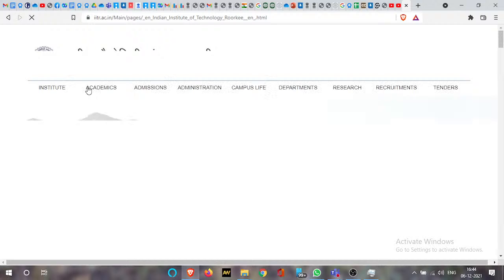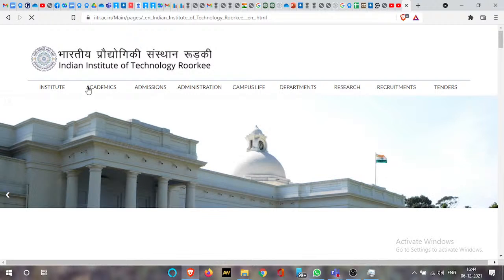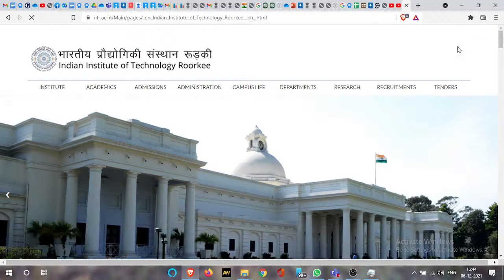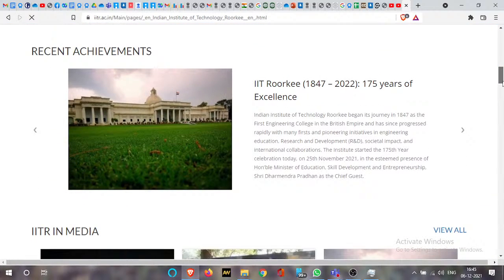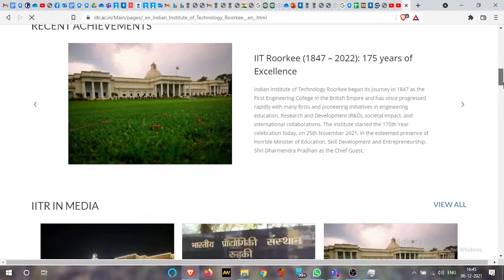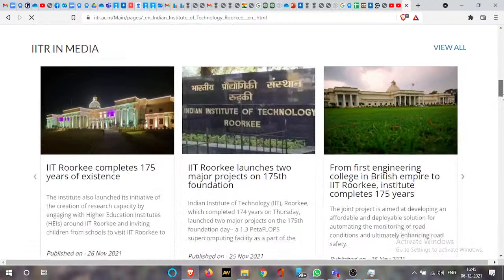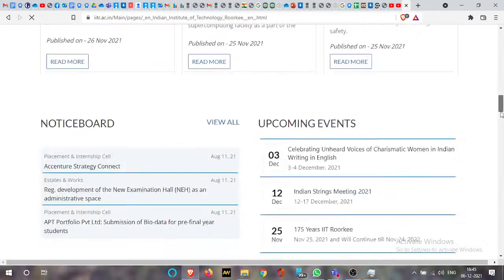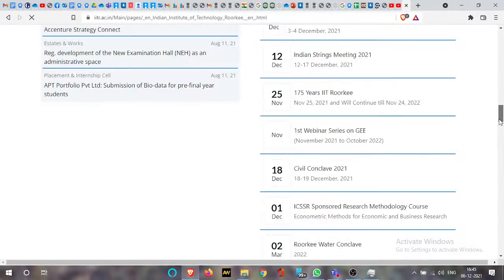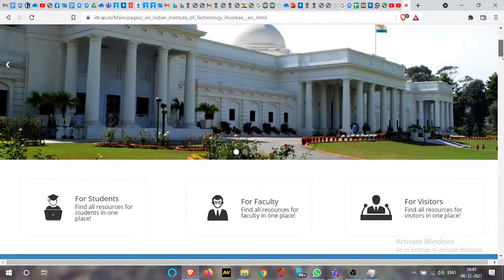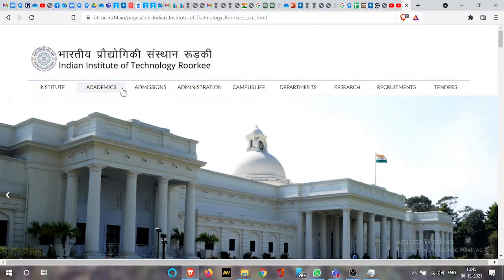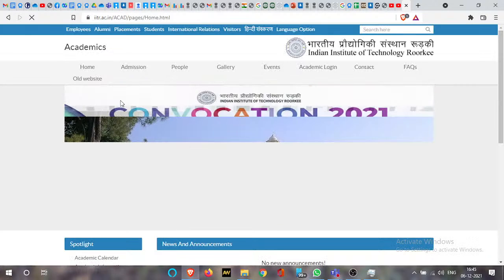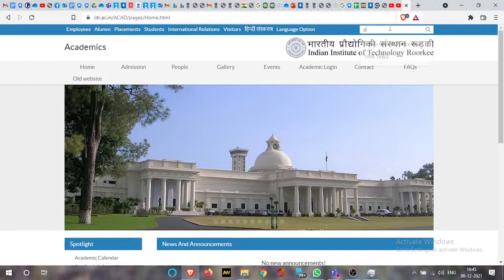So this is basically a cartoon to just show you how spin up electrons can easily transmit through this channel. If the alignment of one ferromagnetic layer and another ferromagnetic layer is parallel to each other, the electron which is anti-parallel to this can easily scatter, but the electron which has the same orientation as this layer experiences a large resistance, and because of this spin dependent scattering of the electron, this response was very high.